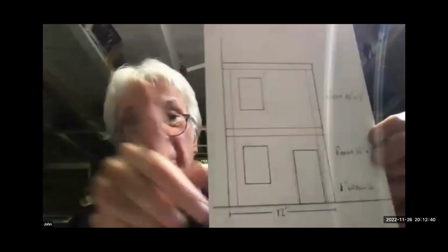That's just a very basic two-room building, and I'd use the mounting board for that because it's relatively thin, quite strong, and it's easier to cut. Trying to cut through a millimetre is a lot easier than trying to cut through 3 to 5 millimetres of foam board. Your blade wobbles, so you can get a much cleaner, sharper line on the card. So I tend to use that for anything where we've got holes in it. I'll use the board, and then the foam board I tend to use for side walls, internal partitions, anything like that.